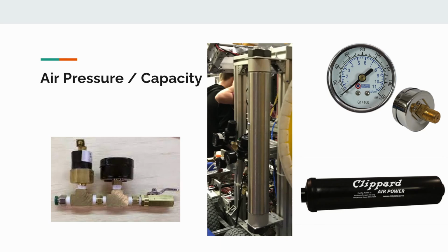This will impact how many actuations of a piston you can do before having to compress your air again using your compressor. The main thing we used for capacity are air tanks, like this or this. Now, the rest of your loop also holds capacity, so all the tubes will have air built up in them, as well as the pistons.